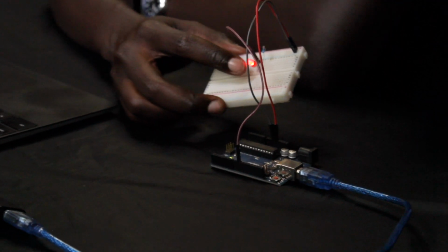The other thing to keep in mind is that because of how LEDs are designed, you might see more of a difference on one side of the scale than on the other. This has to do with the tolerance and the manufacturing process of the LED. So you might see a bigger difference on the lower end when you change the brightness, and on the other end you might not see much of a difference. But again, we'll look at the examples and you'll see for yourself. So right now, this is at 100, which means that on a scale of 0 to 255, it's sort of halfway in between.